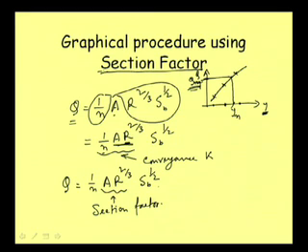So, for a particular channel, whatever the section may be, given the depth we can find area, we can find the wetted perimeter, then we can find the hydraulic radius R, and then we can find out what the section factor is. For different depth we will be getting different section factor. Okay. And for section factor generally a symbol Z is used.